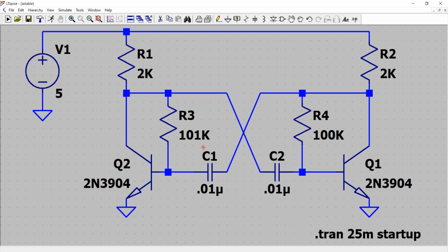Because it is an oscillator, it will use positive feedback in the loop, and therefore it will start producing an oscillation waveform. It could be a square wave, a rectangular wave, or a pulse, and this kind of multivibrator circuit is used to produce delays in circuitry.